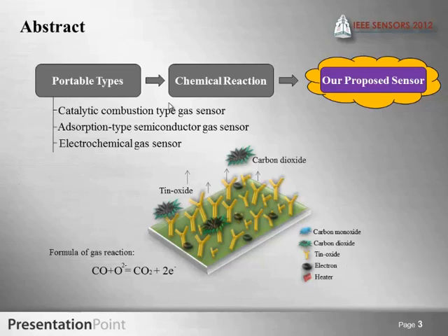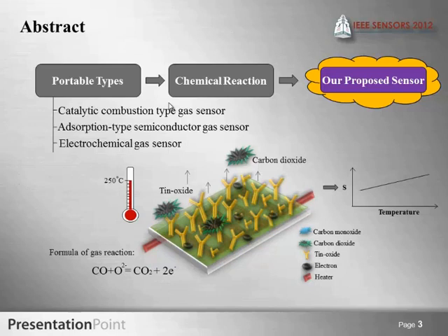Why is this important with our proposed sensor? The conventional chemical sensors usually improve the sensitivity by using a heater to maintain a high operational temperature. Chemical sensor tin oxide can reach high resolution of gas concentration with heating power to maintain the reaction rate. Our proposed sensor abandons the heater and uses the ferromagnetic field to enhance the sensitivity, achieving the same effect as thermal catalysis.